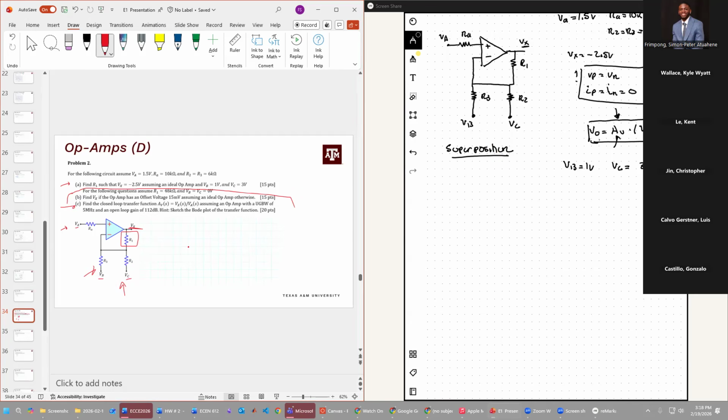If it's a current source, you set the current to zero. If it's a voltage source, you set the voltage to zero. Then you solve each aspect of the circuit individually with all the sources off but one, and then add up the result of each of them. So that's one way we can solve these kinds of problems. Or you can just try and solve it directly as well.